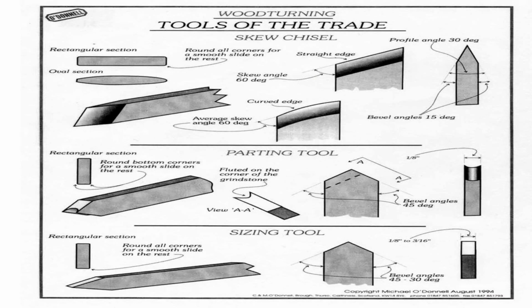It's really a tool that cuts with a burr. So you put a burr on it, or a very, very sharp point. If you're going in straight, you'll cut with the burr. If you have a sharp edge on it, you'll want to ride the bevel and follow the cut down. Any questions on parting tools?